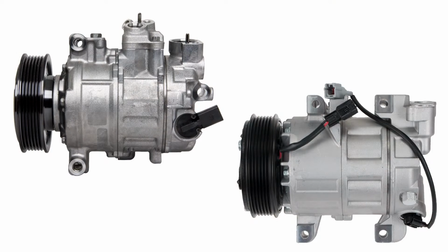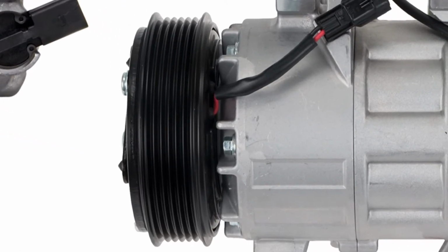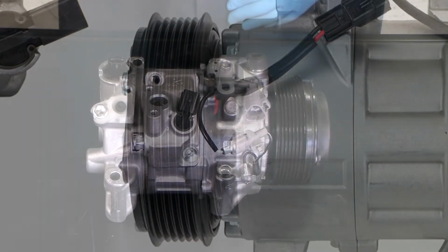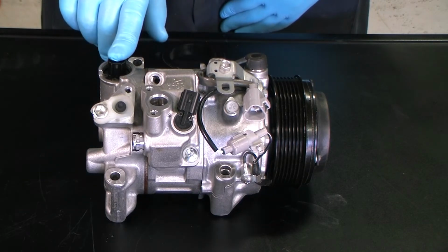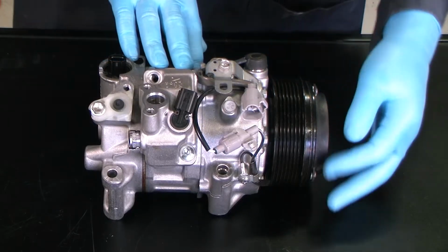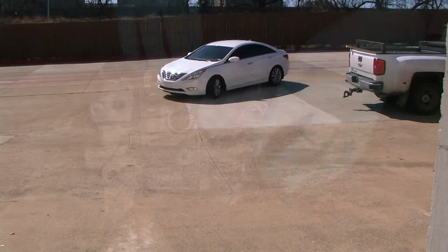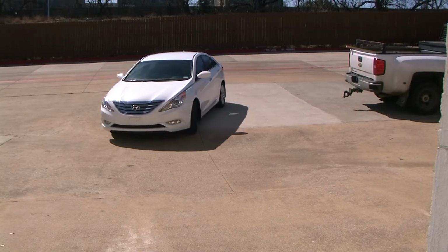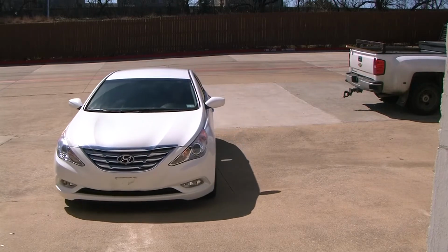More recently, some ECV compressors now have a conventional clutch. For these compressors to work, the control solenoid must be receiving a duty cycle command and the clutch must be engaged. Here is a typical scenario where misdiagnosis of these compressors often occurs.